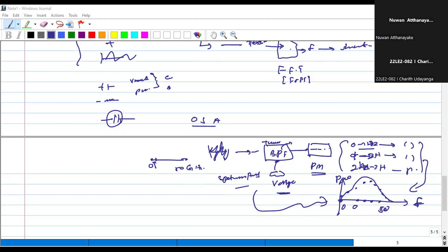And there are other parameters also, that is accuracy. That is the degree of exactness of the measurement compared to the expected value. I will explain it. And resolution is also another very important one. For example, I told you that related to the analog to digital converter, resolution gives us the number of bits to represent the voltage value. When the resolution is high, we can detect very small voltages also.